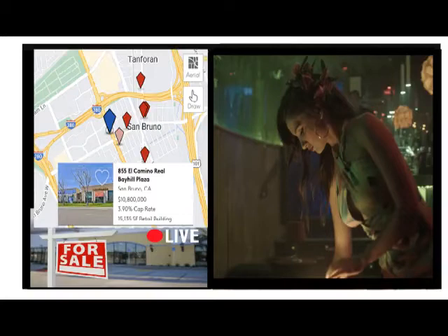Other building components also can be insulated. A fiberglass blanket can be purchased for a water heater and installed by the homeowner. Water pipes can be wrapped to help prevent heat loss. Water pipes wrapped with insulation will be less likely to suffer from the effects of a sudden freeze, which could cause them to burst. The California State Energy Resources Conservation and Development Commission, www.energy.ca.gov/commission/, has established a statewide home energy rating program, revised in December 2008. The residential dwelling seller, or agent, must provide a copy of an information booklet on the program to the buyer.